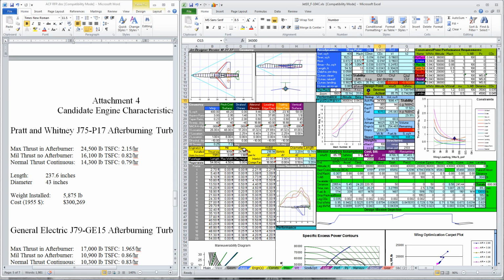And then I think we can probably gain those cubic feet in the forward part of the airplane, up here ahead of the AMAX. So you can see there's kind of a little saddle here. We'd actually like to beef that up a little bit. So let's start broadening the aircraft just after 20 feet, 21.6. Let's go wider, 5.5. That helped a little bit. Let's go 6. And we've got our volume. Maybe we'll go back to 5 there. Maybe we'll leave that alone.